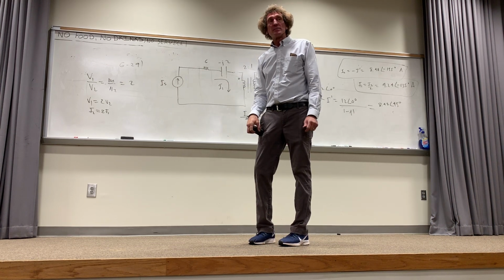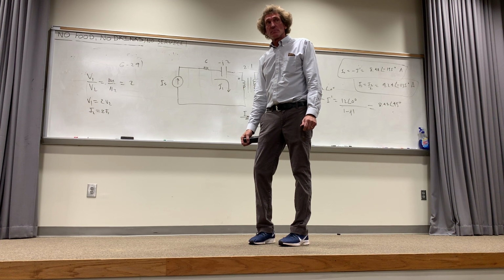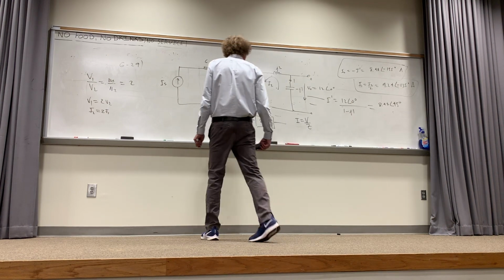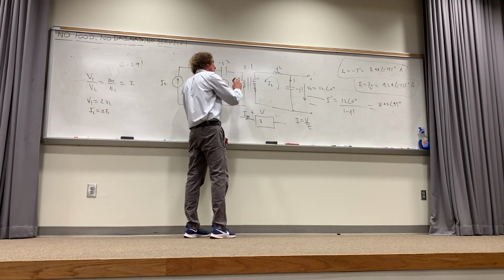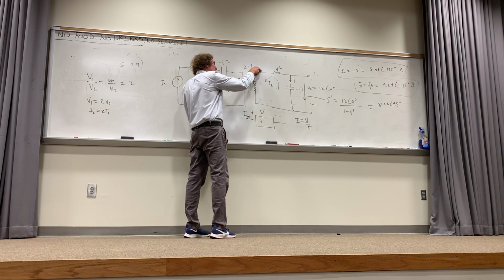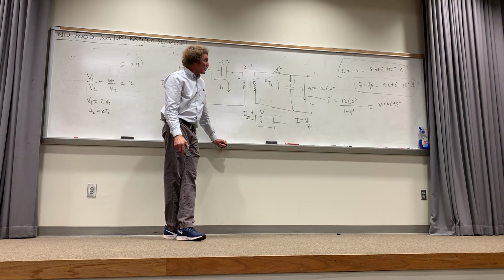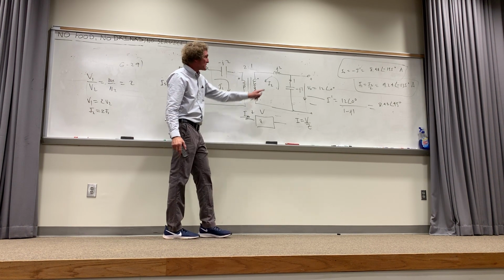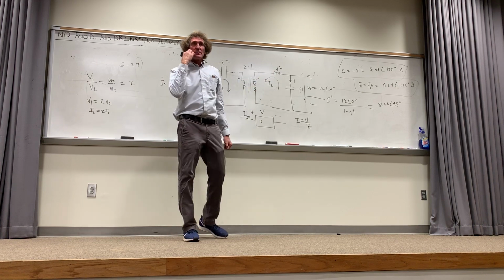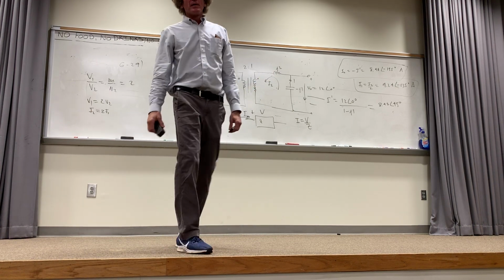Yes? Theoretically, if that was a mutual inductor, could you also have another inductor that's just part of the impedance? Well, if there's a mutual inductance, dot, then you're going to have j omega L1, j omega L2, and then j omega M there, right? Okay, I'm just saying, there wouldn't be an extra inductor in those problems, right? You mean this? Yeah, you could put an inductor in. That would be when you just treat it like the impedance.